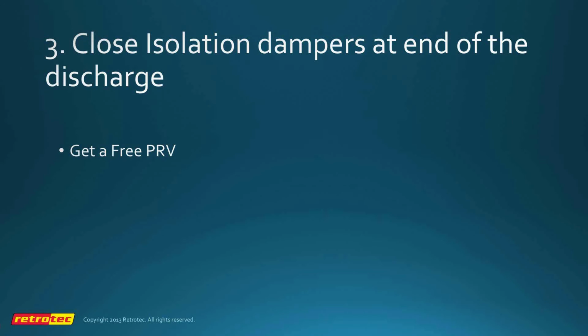Obviously, if that system is running and it's going to be sucking air or agent out of the enclosure and allowing air to be blown in, that's not such a good thing. Even at that, the pressure venting aspect of keeping the isolation dampers open has a fair bit of value. So it should be considered, particularly in situations where you have no ability to install a PRV or the enclosure is already built.